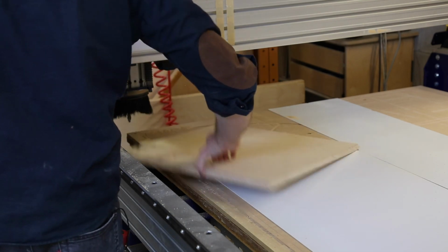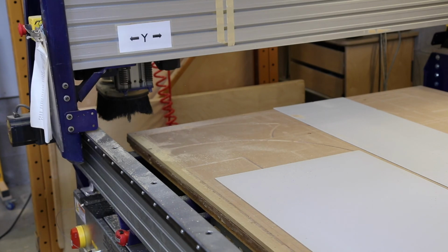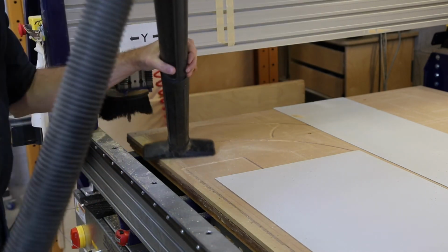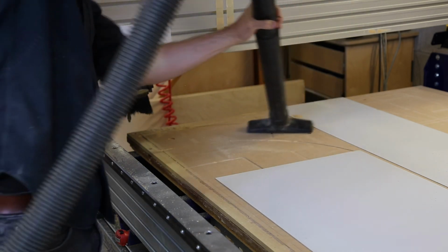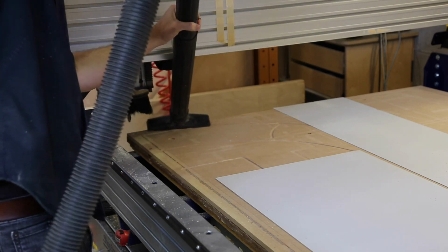If the tabs rip out, they may break and damage your workpiece. This is a significant problem with Baltic birch plywood or other veneered boards. If necessary, slip another sheet under your work so that it is supported as you move it from the CNC bed. Vacuum off the spoil board and sweep underneath the CNC router.